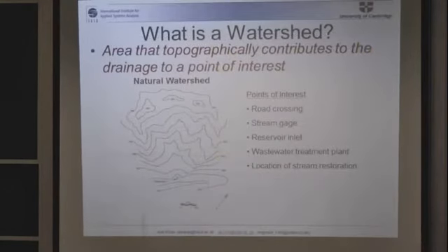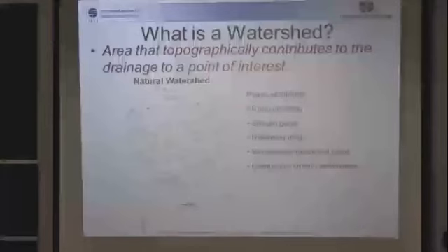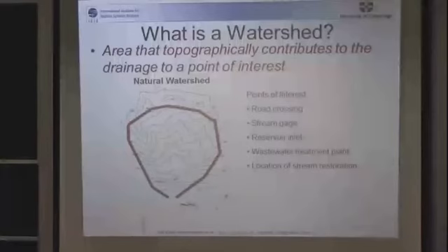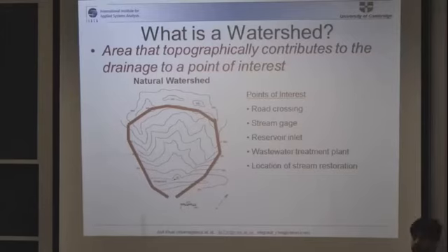What is a watershed? A watershed is a topographical division which provides water to a single point, which is known as the outlet of that basin. So if we look at the contour map, one can cleanly draw a basin over the contours, if one wants to draw which points will contribute water to a single point.